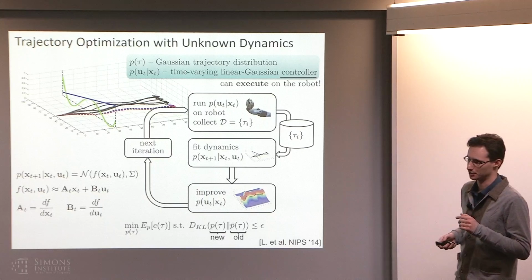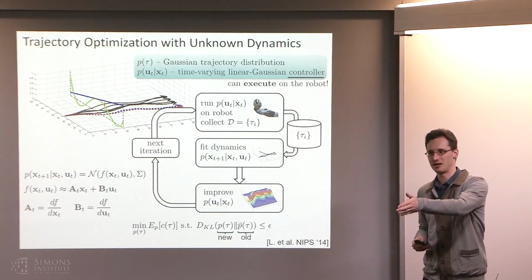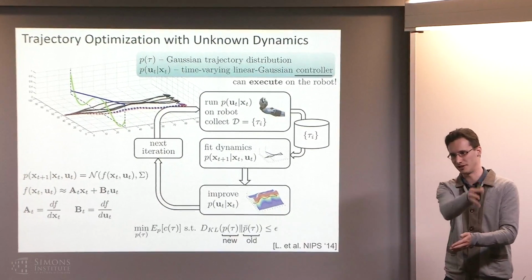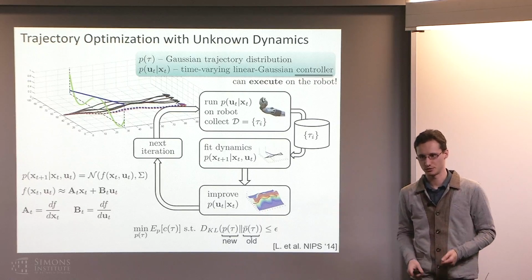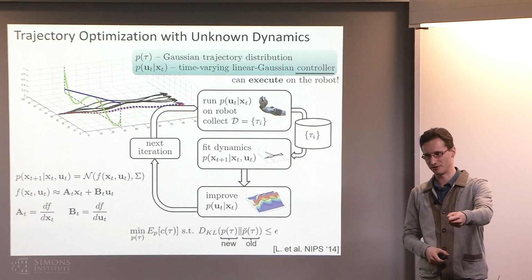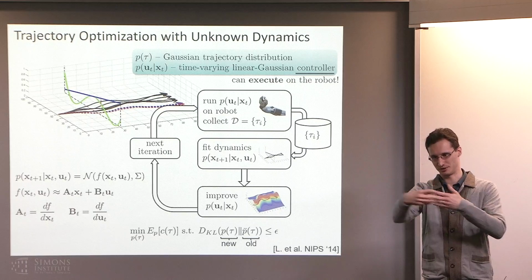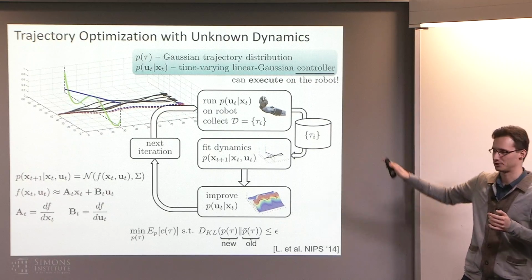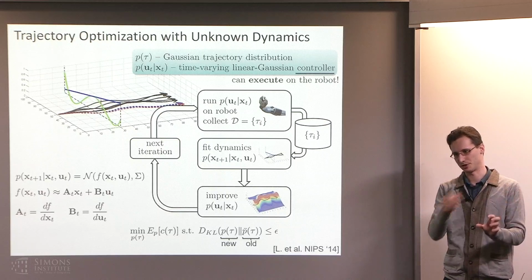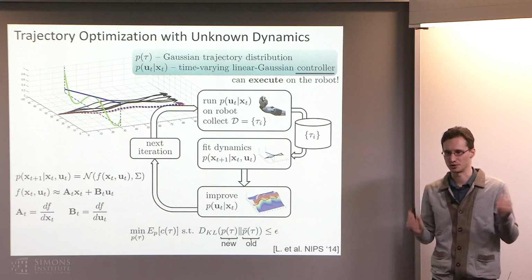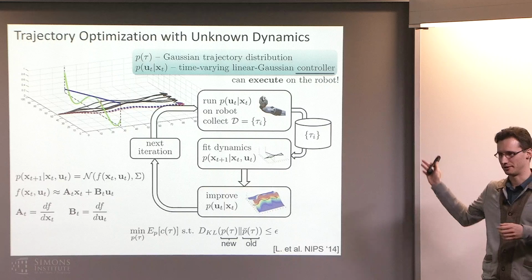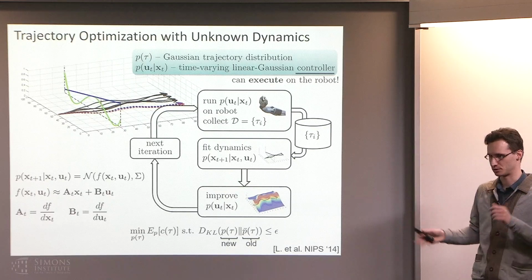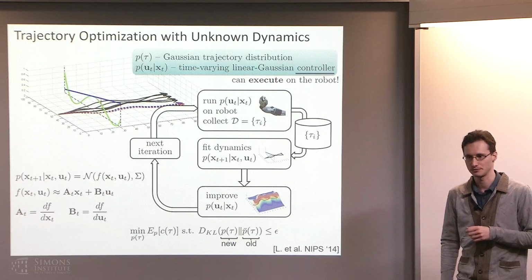One way you can mitigate that is, the reason that I mentioned this is because in the quadrotor case, maybe one of them collides with the tree and the other one doesn't, right? So you run it 5 times, 2 out of the 5 collide, 3 don't. You try to fit a line to the ones that collide and the ones that don't, and you're in bad shape. There's a little trick that you can do to fix this. You can basically just cluster the trajectories and then fit the linearizations. That works fine. We haven't tried to do it on an actual quadrotor yet, but we have done this clustering trick with the manipulation tasks.